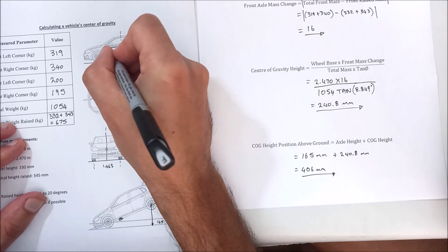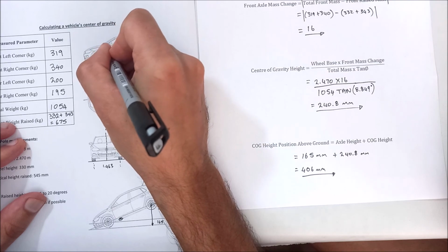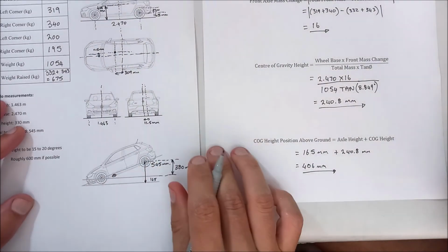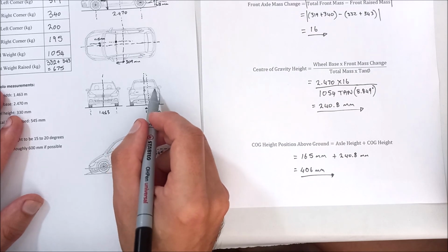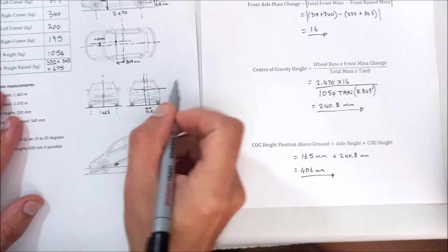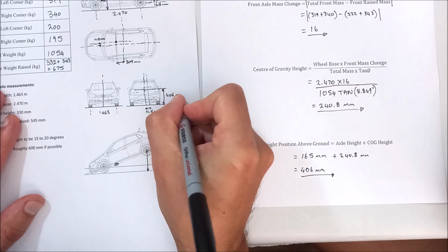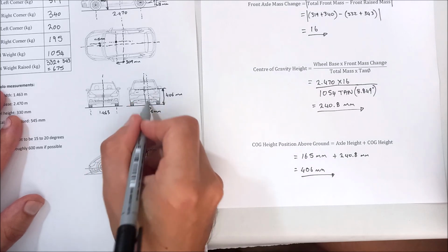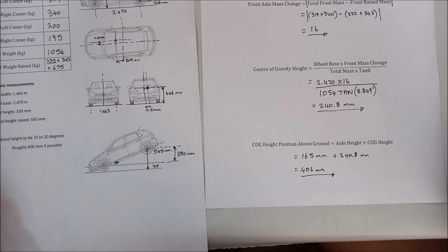That would be a distance of 406 millimeters. If we look at it in terms of the vehicle from behind, 406 millimeters would probably be roughly over there. Okay, so that would be 406 millimeters. And then, therefore, those two lines are intersecting over there, so our center of gravity will be located roughly over there when looking at the vehicle from behind.